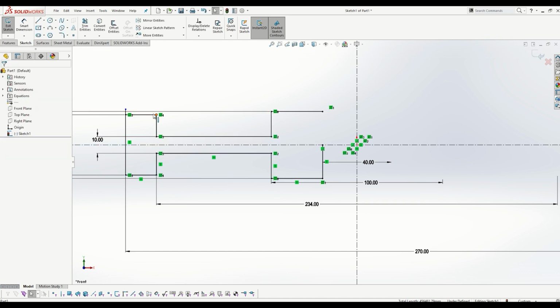So I'm doing that. And one more thing, why these two I am not mirroring? I mean this vertical one I did, I'm just adjusting that relation. Why am I not mirroring? Because if you mirror, those two entities will be connecting here. That will be considered as open, a separate part. We are not doing separate things; we are just doing one cross section.